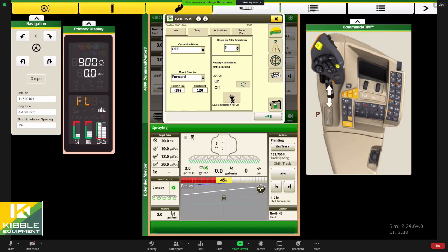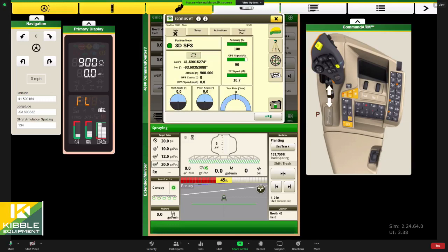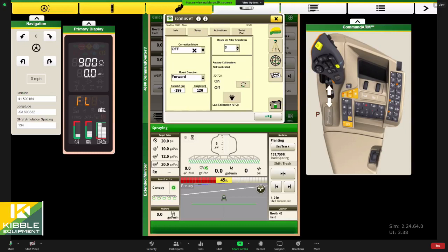And Margot, this is a 6,000 you're simulating here, but with this new software update for a 3,000, we've seen the very first time you turn on the receiver after February 1st, there's a checkbox that we don't have on the 6,000 that says default frequency, and you have to make sure that box is checked so you can steer. Yep.